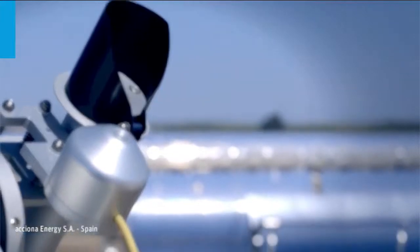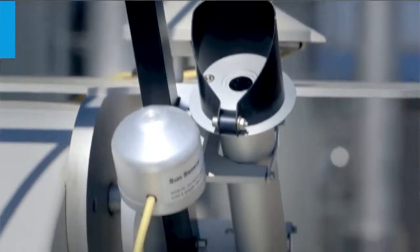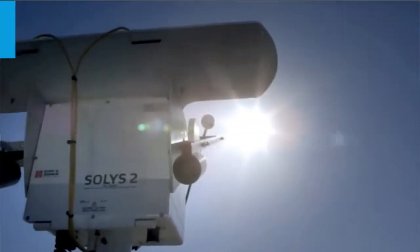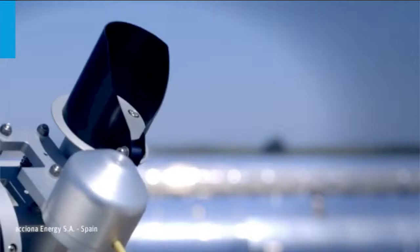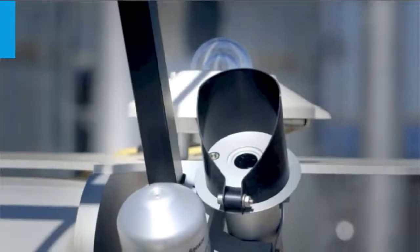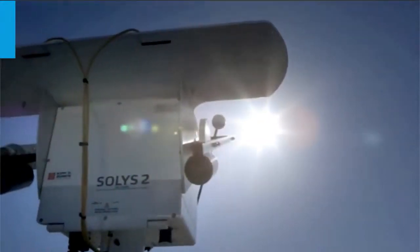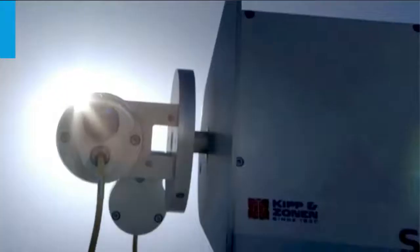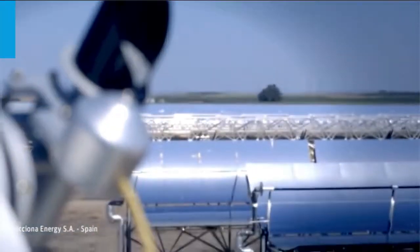Direct radiation from the sun is measured using a pyrheliometer. A pyrheliometer has the same principle as a pyranometer. It also uses a black absorber and thermopile detector to measure the amount of radiation. But it can only see the sun, as its field of view is limited to 5 degrees, as you see in this movie. To keep the pyrheliometer pointed continuously at the center of the sun, the instrument must be mounted on a high accuracy automatic sun tracker.